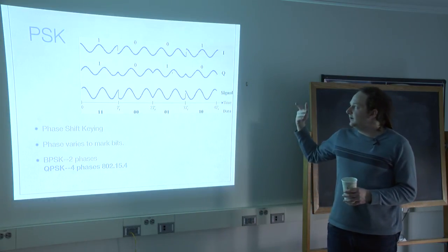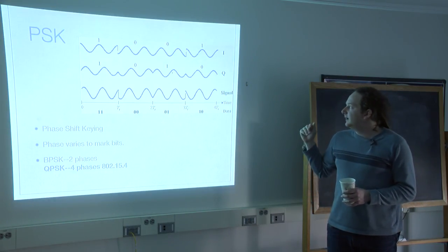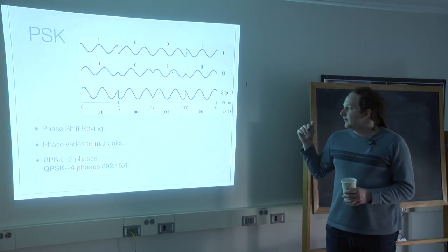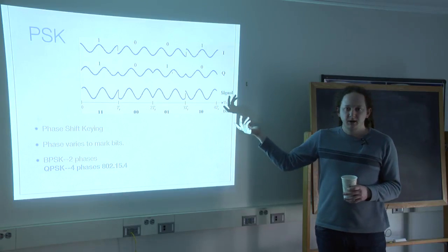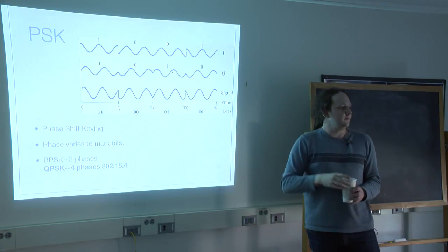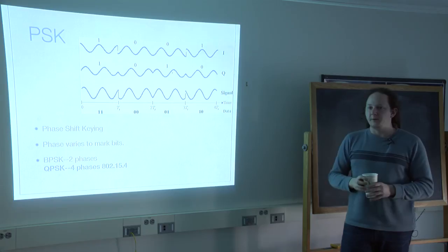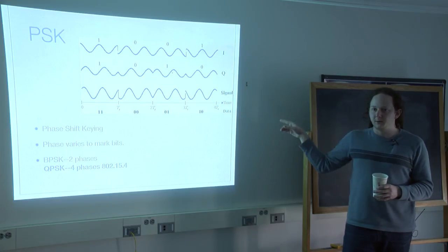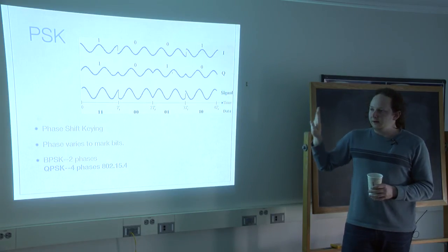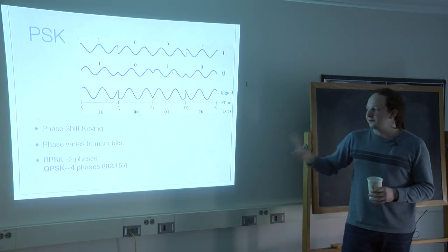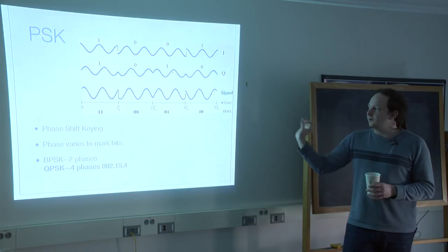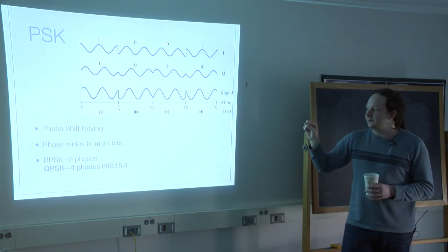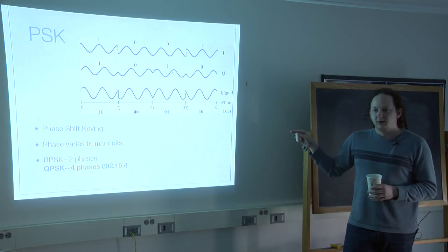There's also phase shift keying, where the phase of the signal is inverted. This is what Zigbee uses. So in the earlier diagram, when I showed you the 32 ones and zeros that would represent a given nibble, each 4 of those were a single symbol at QPSK. And this is also why the shifts nicely aligned into sets of 4.